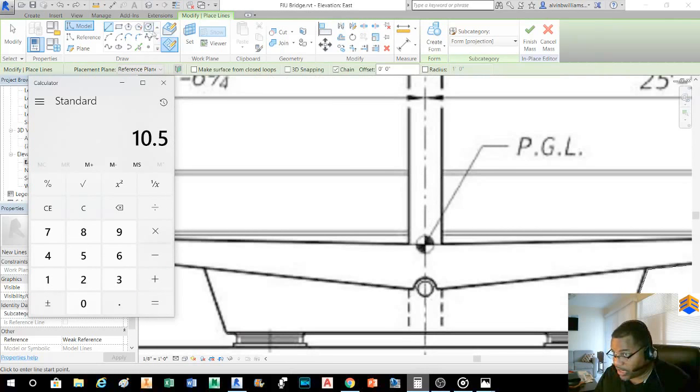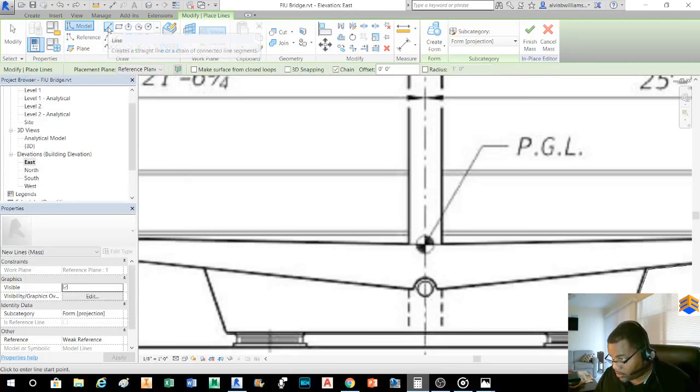So let's see if we are, and now what I've clicked is the line tool again, and I'm going to type in 0, 10.5. That's the same as typing it. Oh, yeah, sometimes the program does this. I'm not sure why, but 0, 10.5 inches.